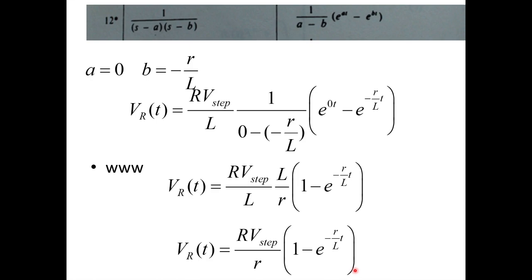So again, I'm going to reiterate what happens. We had a differential equation in time, and Laplace transforms allow us to convert our equation into the spectral domain. In the spectral domain, differential equations are handled like algebra. And once we solve for the variable we want, which was the current through the system, then we can transform back to the time domain, because the time domain is how we're going to measure it with an oscilloscope.